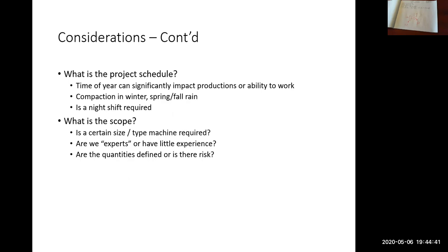So what's the project schedule? So time of year can significantly impact productions. So for us here in the Lower Mainland, digging in silt and clay in the rain is basically impossible. It becomes just muck. You can't do anything. Your equipment gets stuck. You can't get trucks to your excavator. It doesn't work. So that's an example of time of year.